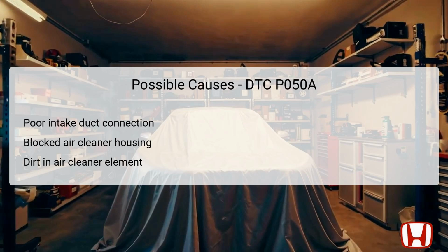The first potential cause is a poor connection or a blockage within the intake air duct, which could restrict airflow necessary for optimal engine performance. If airflow is restricted, it can lead to improper idling, especially when starting cold. The second possible cause is a blockage or poor connection at the air cleaner housing.